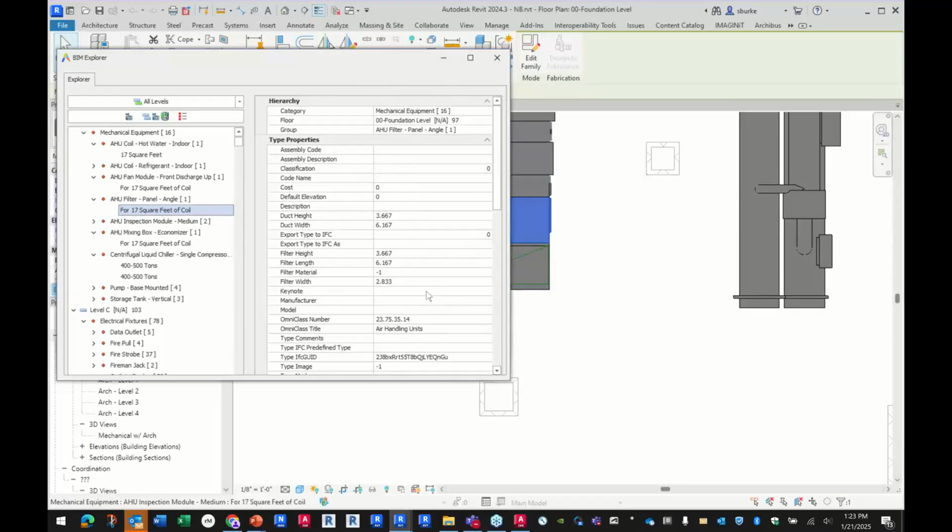And the key here, when thinking about facilities management, is that everything actually starts at the design stage. It actually starts at the facilities management tool. So you have an FM tool, whatever that may be. Again, we're talking about Archibus here, and it has a set of values or parameters, information that it needs. So you ensure that information is part of your BIM execution plan. It becomes part of your design, and you make sure that the Revit data has those fields, and then you can map them if they're named differently, mapping certain fields from the Revit model to the fields that are required in the Archibus environment. But now I have this nice bi-directional tool. As I update my Revit model, I can update Archibus with that information.